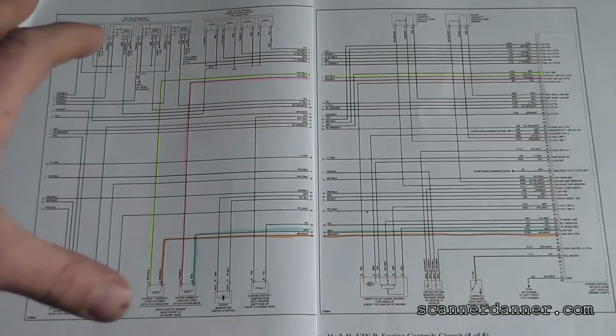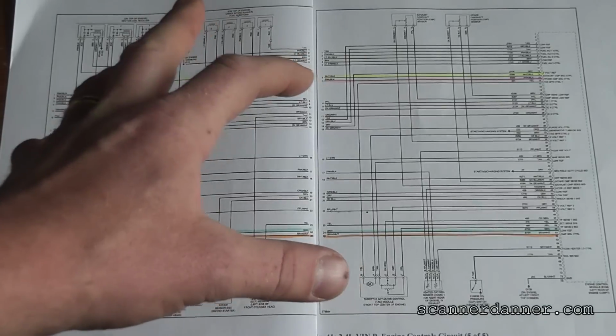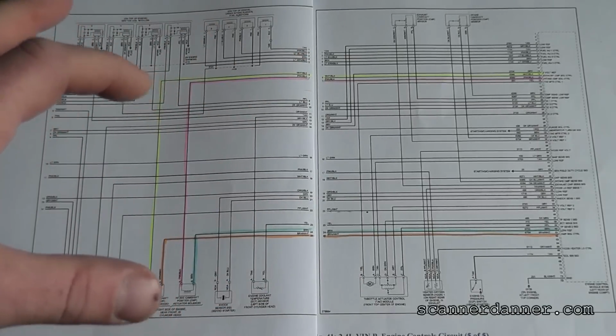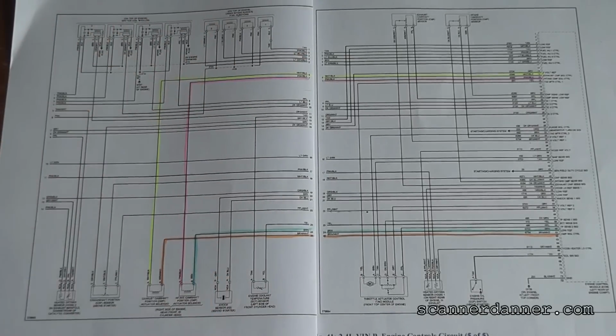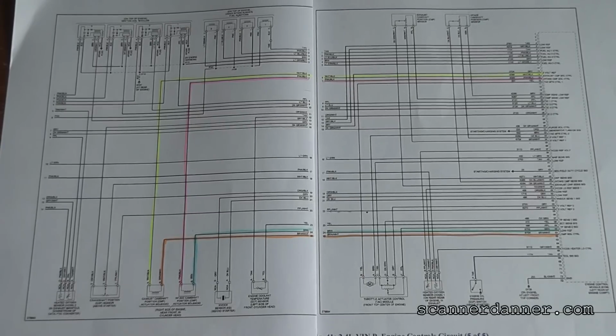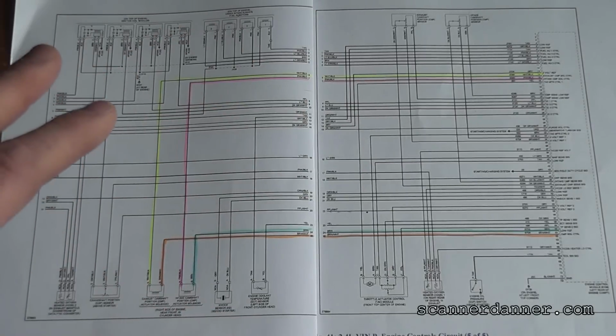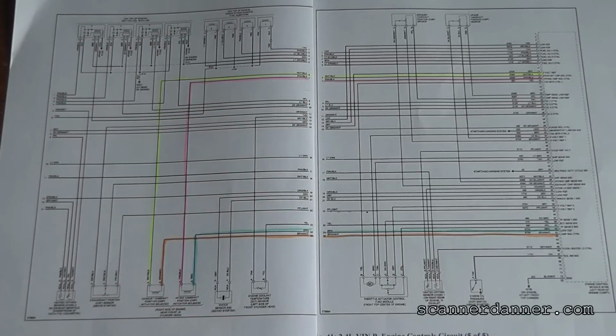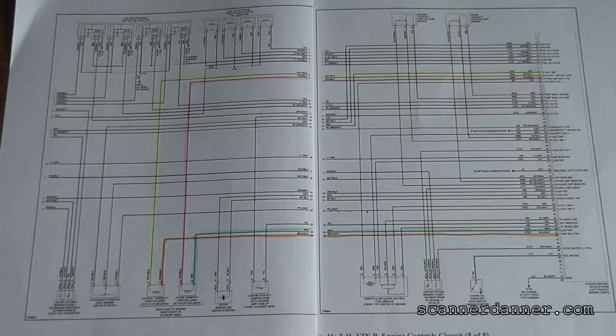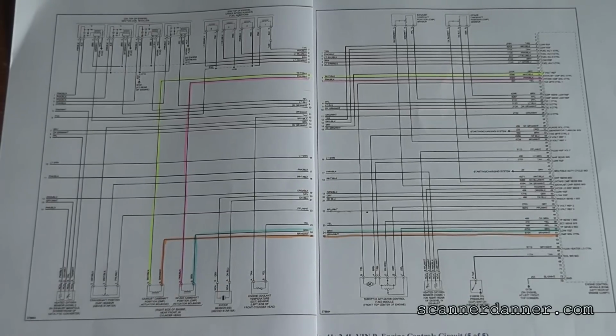The injector control wires, both positive and negative, go to the computer. However, they're both controlled. Both the power and ground are controlled. So we need to be careful when it comes to manually energizing these kind of circuits, because there are variables to them. Now we'll see what this entails when we get to the car as far as manually energizing the circuit, or if I have bi-directional controls on the scan tool. I don't know yet if I will or not.